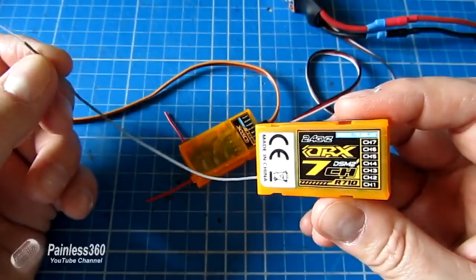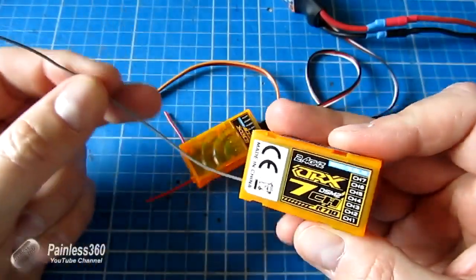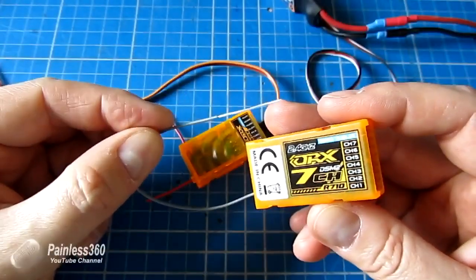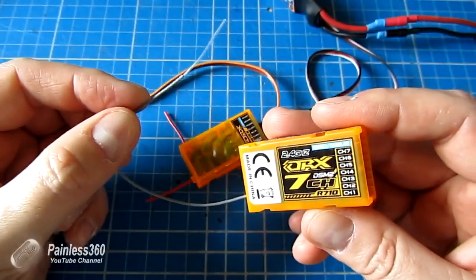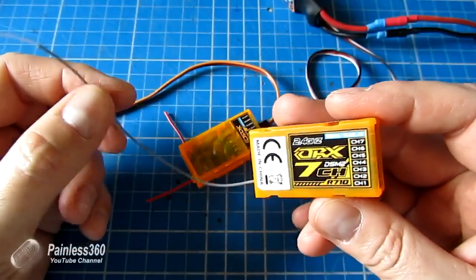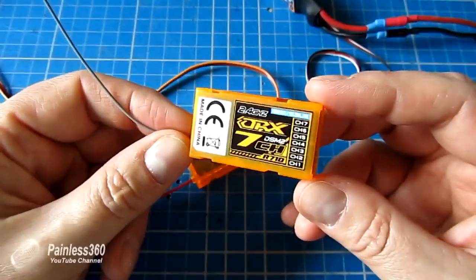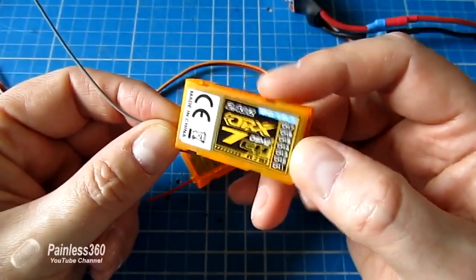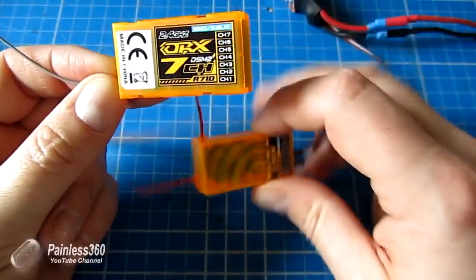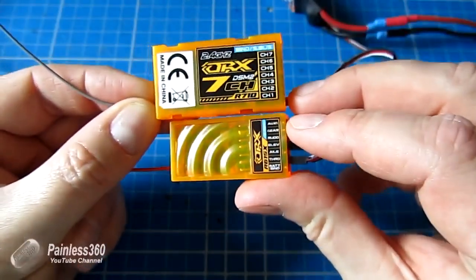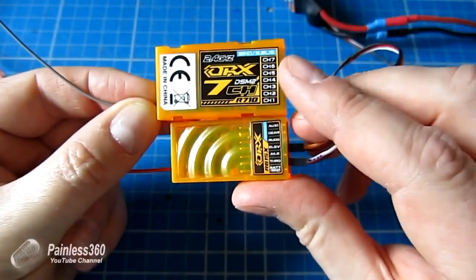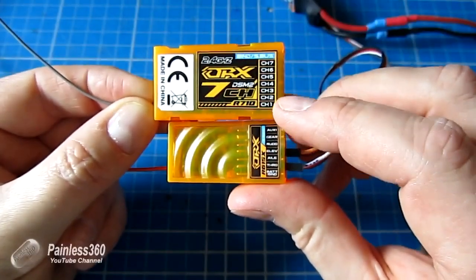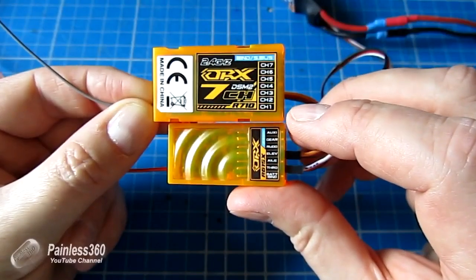The reason being is that carbon fibre absorbs the radio signal that's coming from the radio, because 2.4 gigahertz doesn't go through things very well at all. But here you can actually see you've got the different channels listed out. Now they actually are going to be pretty much the same as the ones on this other receiver, but on this one you have to find your manual and figure out which is which.